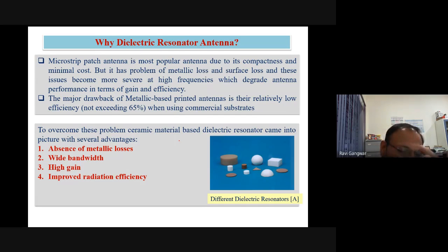The first thing is that they are very selective in nature, which means the quality factor is going to be very high. Second, their permittivity value, that is epsilon r or dielectric constant, is very high. Third, this ceramic material is enclosed with metallic boundaries, a metallic structure. Due to these three things, that piece of dielectric material is going to be highly oscillating in nature. That's why they are used in oscillator or filter applications.